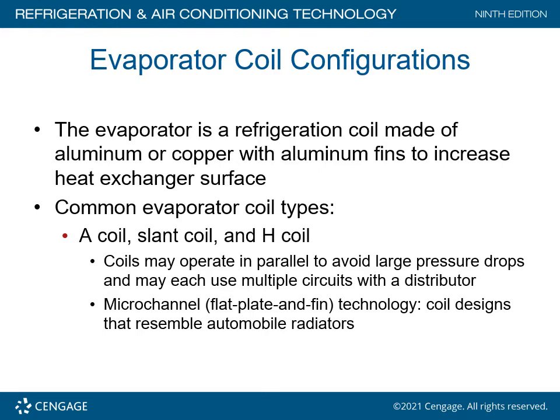The manufacturers have pretty much given up on copper and aluminum fins because of the expense and corrosion and dissimilar metal problems. So on your new coils today, and I'm talking about 2021 now, basically we are utilizing all aluminum coils. And for the most part, it appears to be working. I think the jury's still out on longevity, leak issues, things like that. But we do not have the issues with dissimilar metals taking place.